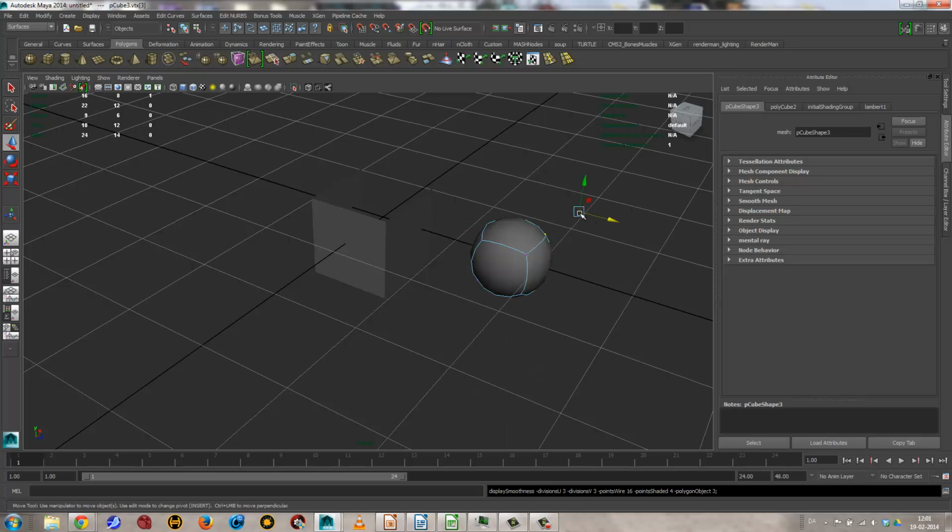You can see I'm actually seeing that vertex up here when I grab this point down here. So this is like the projection of that vertex down on the smoothed version, and if I move that, I can deform this sphere that is actually a cube. It differs from program to program, but generally most people are using what's called Catmull-Clark surfaces today. It's a Pixar development at some point, which takes the same sort of mathematics that is used for NURBS and applies them to polygons.